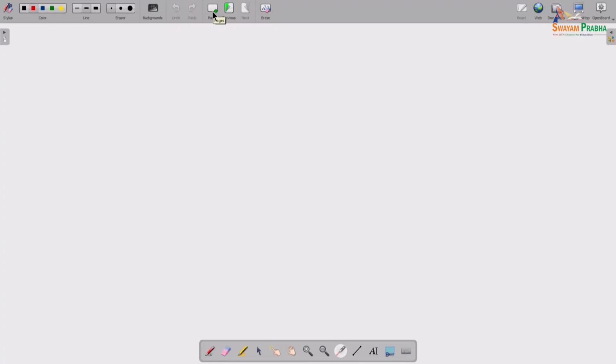All right. So, as you can see, we've come up with several lengths, right. You have the boundary layer thickness, displacement thickness, momentum thickness, and of course, the axial length along x. So, the flow is happening, and then we should be able to discuss several different types of Reynolds numbers, right, because now what do these things depend on and how am I going to calculate that, etcetera. I think those are questions which we will need to answer, right.